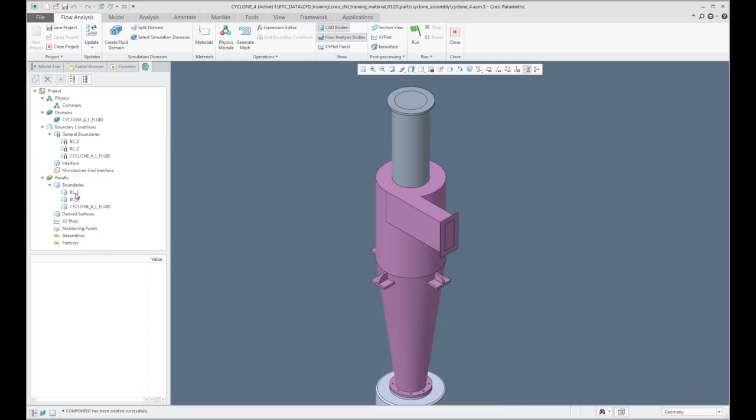That's an interesting point to note there, because when I say go and add this model to my assembly, what it also does is, by virtue of the fact that we had holes on the ends of those openings, it automatically finds the fact that we need to apply boundary conditions at those openings as well. So it's already picked that up for me, so it's got the intelligence there. So this is part of the ease of use aspect. So we have the volume inside.